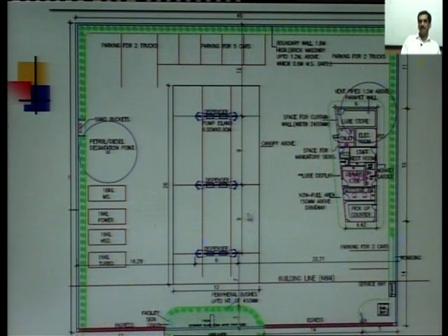To have an uninterrupted power supply, we need an electrical room and an electrical panel, and apart from that, every other piece of equipment in this petrol pump is fully secured by means of earthing. We intend to have earthing for every island, every machine, every tank, every light, every building and every room. Lots of care has to be taken for the earthing, so that our equipment does not get damaged.